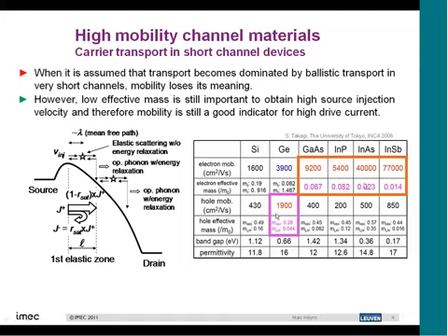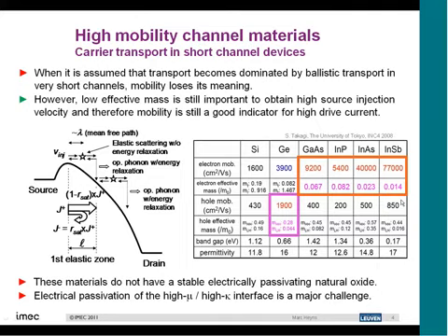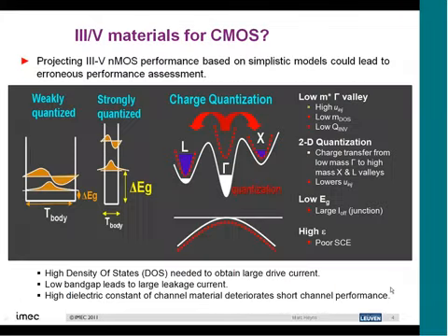So the question is, if this is so obvious, why has this not been used in the past? Well, I think the big difference between these materials and silicon is very simple. With silicon we have this fantastic, beautiful interface between the silicon and the silicon dioxide, which gave us the possibility to make MOS kind of devices. Unfortunately, we don't have that for these high mobility materials. So electrical passivation of these materials is a major question, and it's a very big challenge.